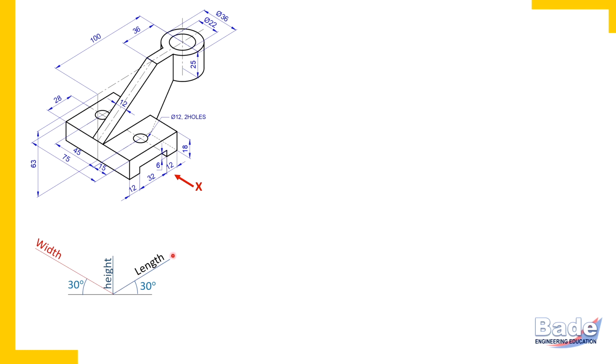Focus on all dimensions which are parallel to length axis. So in this orientation, at top we can see from extreme left end of the object up to the center of the cylinder, the dimension is given 100 mm, and extreme right edge of the object is curved edge. So we'll have to add a radius of this curved edge, and this curved edge has diameter 36. So radius is 18. So 100 mm plus 18, extreme left to extreme right. That is overall length of the object, and it is 118 mm.